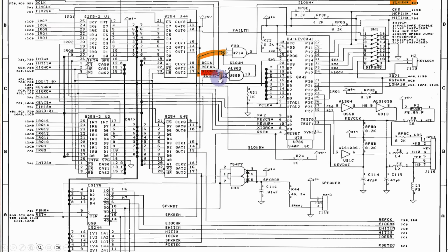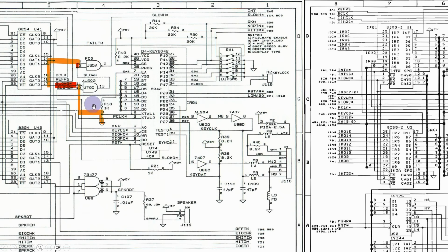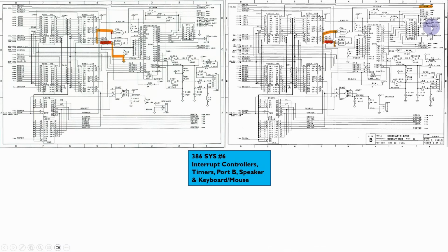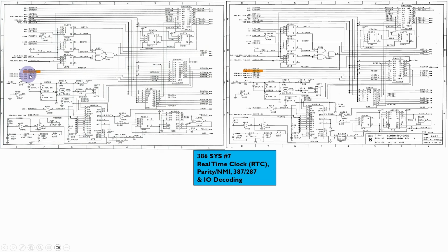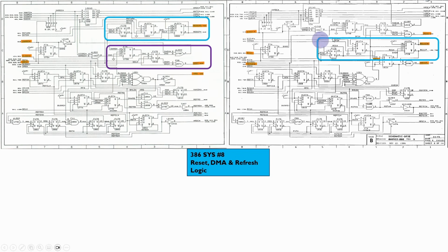There's an area of the logic relating to the speed control. So this was manually changed on this particular version of the document. When I've been doing the KiCad diagrams for this, I've actually implemented this, and you'll see over here that there are differences: this was the original diagram and this has been the modified version of it. There's an additional signal at the top there. And just some of the labels and things were relabeled between the two versions. And you'll see here on this particular one, there are some differences in the labels, but in fact, the logic here was moved down here and the logic here was moved up here.